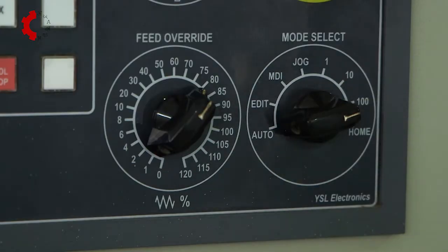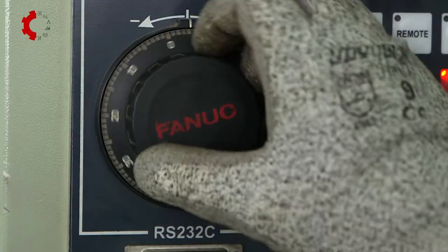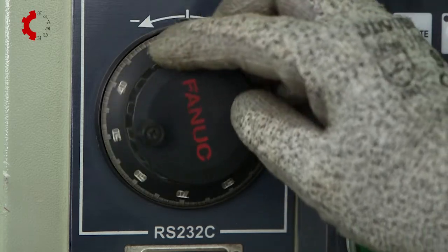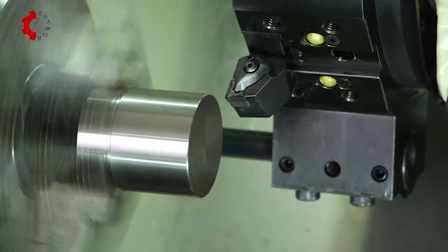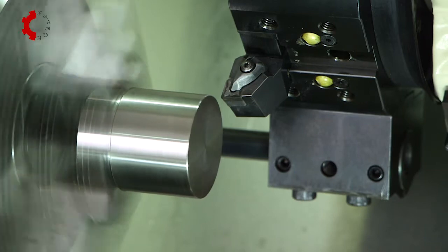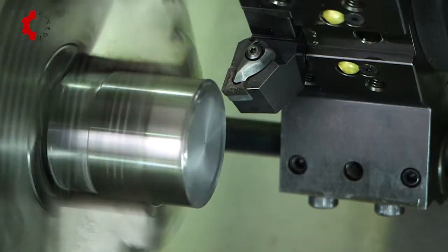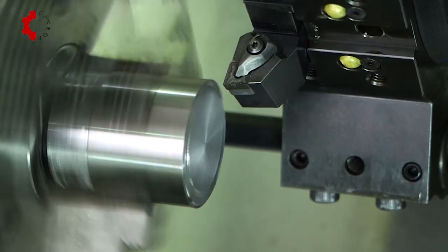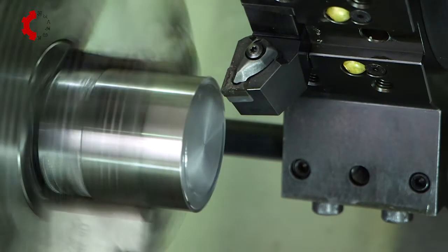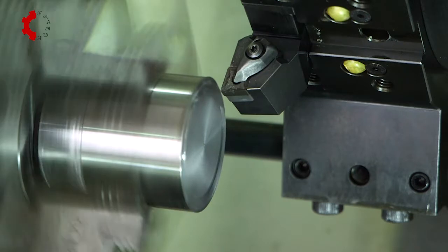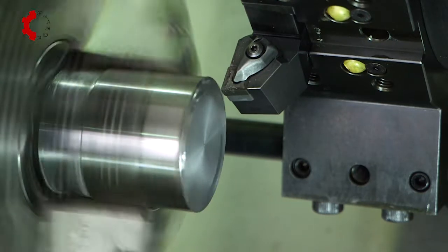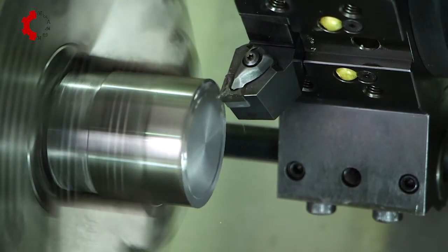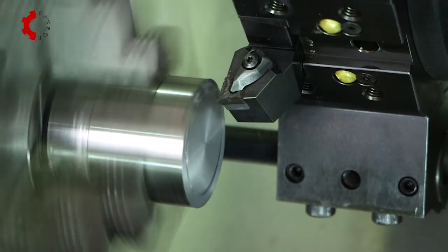Switch to manual mode. If the spindle stops, start it again by using the manual pulse generator wheel, MPG, also called electronic hand wheel. Move the tool so that it gently touches near the maximum diameter at the front face of the workpiece. Move the tool in X plus direction to clear the workpiece, first switching MPG to X axis. Move the tool in Z minus direction by a small amount, first switching MPG to Z axis. Switch MPG to X axis and take a small cut from the front face of the component in X minus direction.